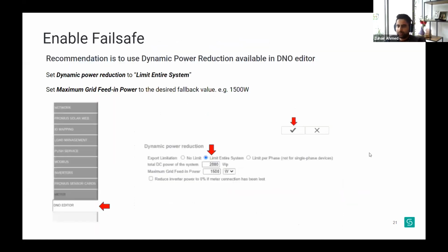After enabling Modbus TCP, the user needs to put in a fail-safe. I should explain it this way. In an event where the Droplet loses comms with the inverter, we need to make sure the inverter knows what to write so that it is in a state where the Droplet, if it comes back online, will be able to rewrite the controls.